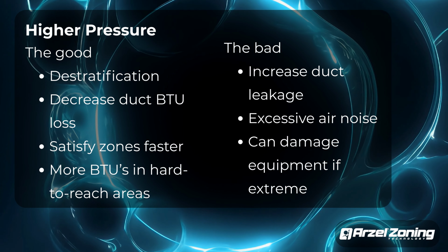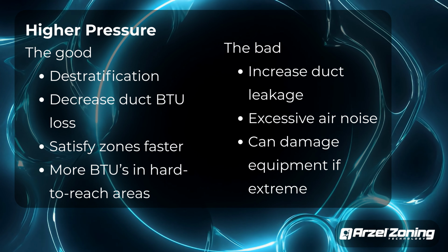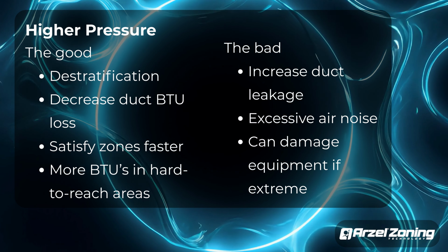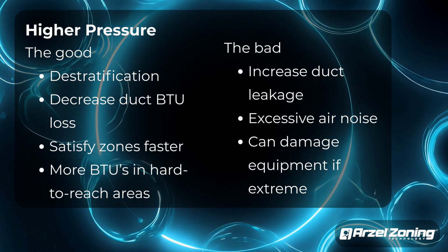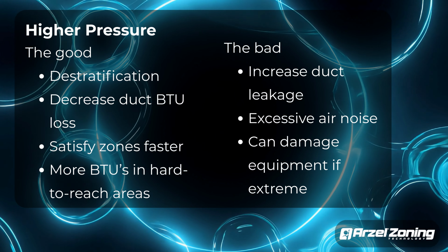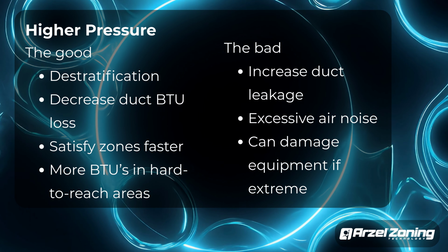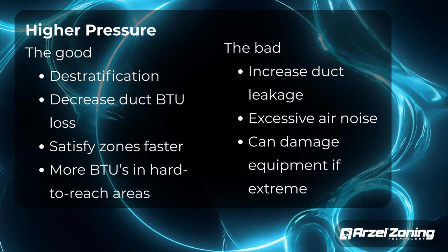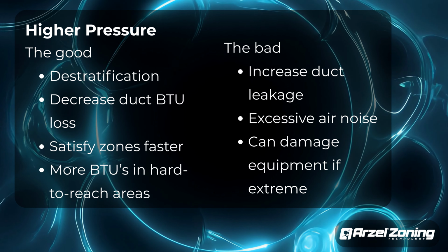So in other words, there's a lot of second floor bedrooms when this AC system is running, you have to stoop pretty low to tell whether the AC is running or not, because the air is just kind of barely coming out of the register. The increased static pressure is going to give you that velocity and throw to shower the ceilings and the walls and get that air moving and stop that.